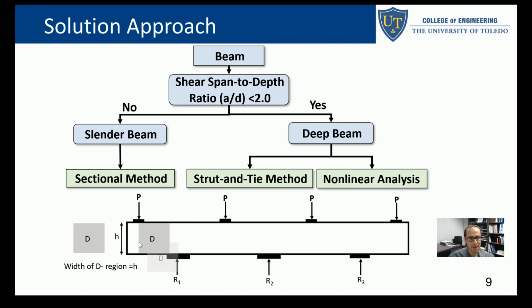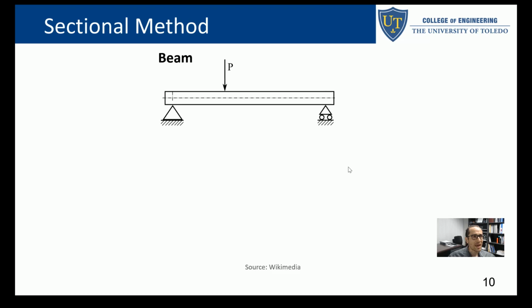So they overlap very significantly. Here the shear span to depth ratio is a bit over 1, which is a very deep region. So keep doing that, and as you can see for this pier cap, your squares would be overlapping, and you're going to get an entirely deep member, which is a very common situation for pier caps.